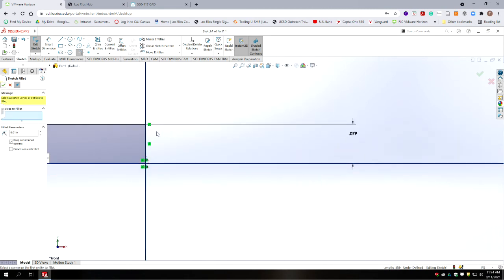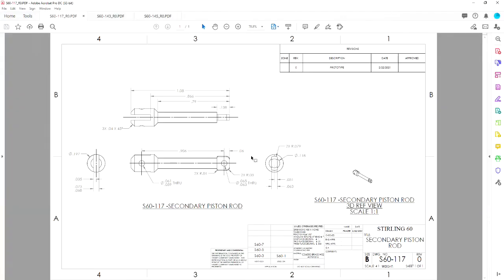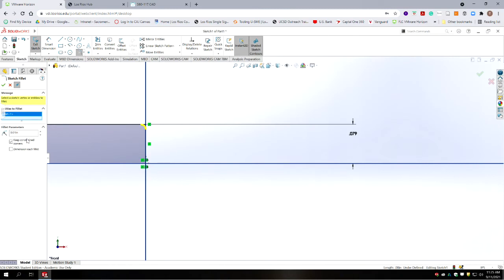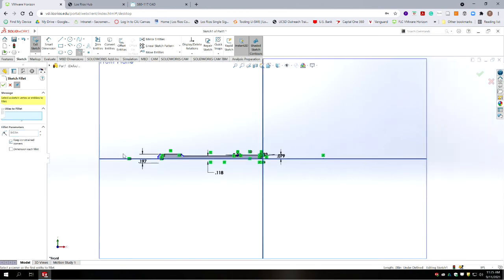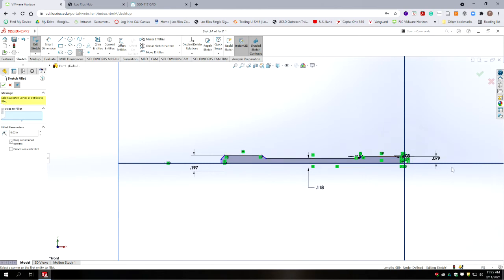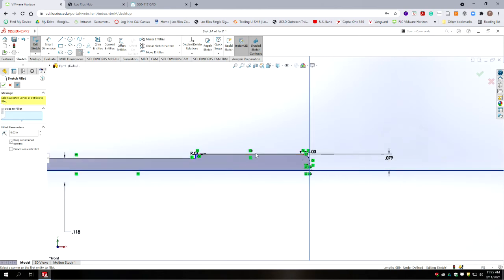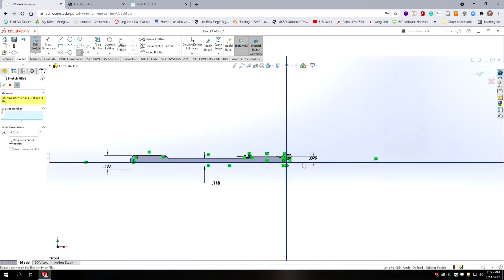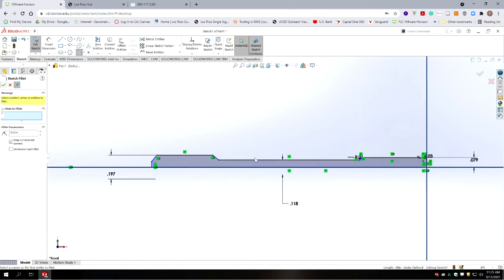And then we have another fillet on this side that's bigger. Select our 2 segments, and if we reference our drawing, it's 2 times 30 thousandths on that side. So we just have to bump this up to 30. All right. You might get an error about something not being defined, and it's because it has to update with the dimension that was there. And occasionally you have to just recreate the dimension where a corner was referenced. Okay, so we've got all that established.